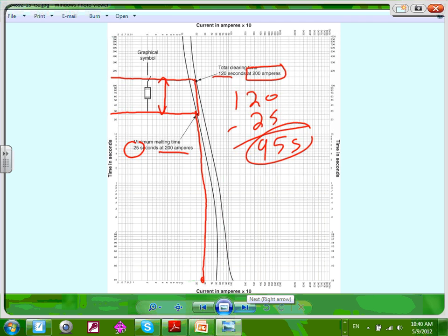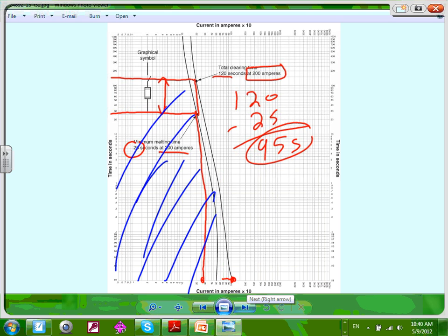This point here, if you have a short circuit higher than this point, Chris, you get yourself a big ball of fire. This area is the area that's protected. Anything to the right of the fuse or the circuit breaker is what's protected. This area is called protected.